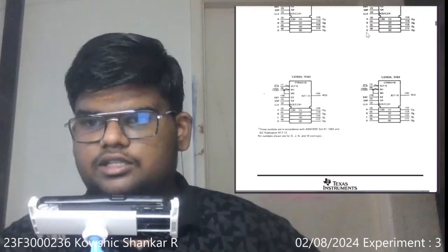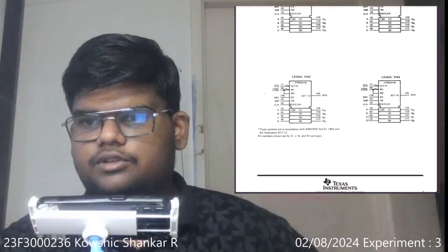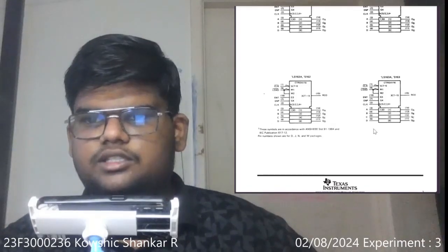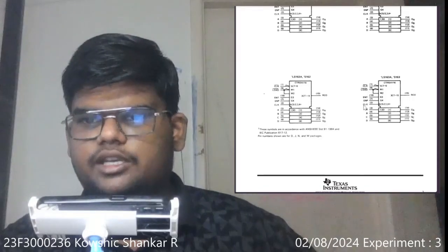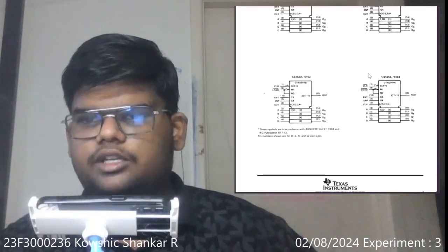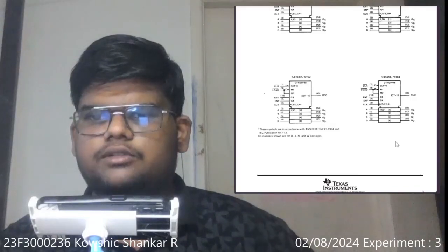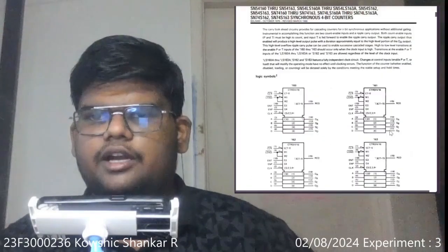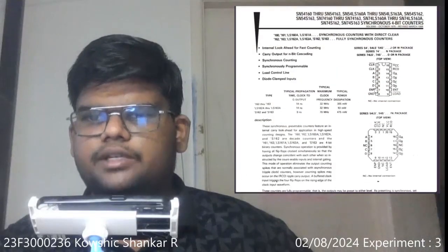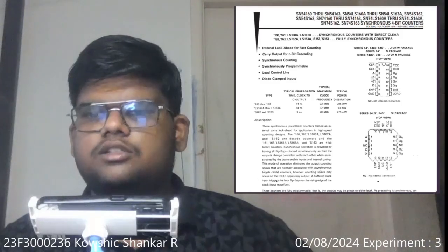And here is the diagram for 74LS163. It seems that CLR, load, ENT, ENP, CLK, A, B, C, D are all inputs and RCO, QA, QB, QC and QD are outputs. I have searched on the internet and got to know about the pin CLK, which is clock. A clock signal is a square wave which is used for synchronizing electronic devices.